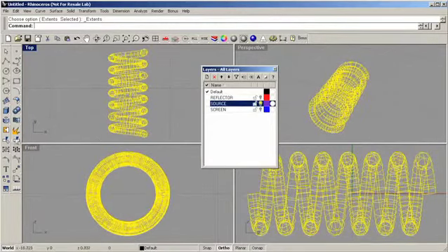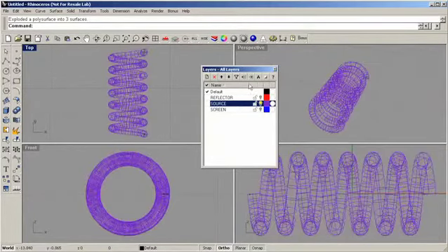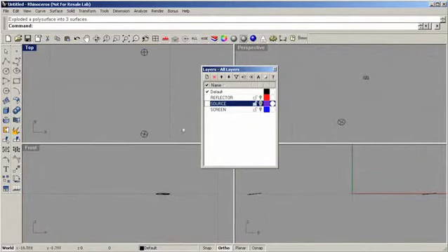Okay. Now I'm going to do an explode on this object. And I'm going to place the helical portion of that object into the source layer, leaving the 2 end caps. Now the end caps will not be specified as emitting surfaces. If we want to include those in the ASAP model, we can. It will have very little effect on the analysis result. At this point, however, what I would normally do is just delete these guys.